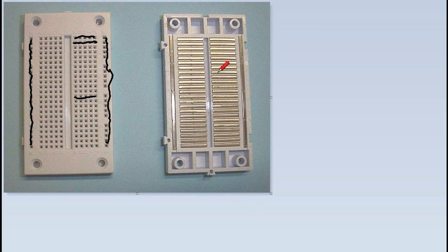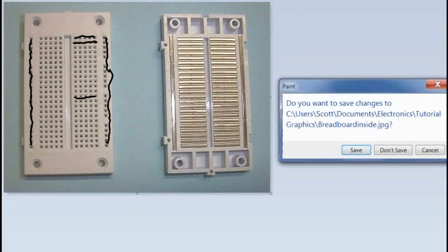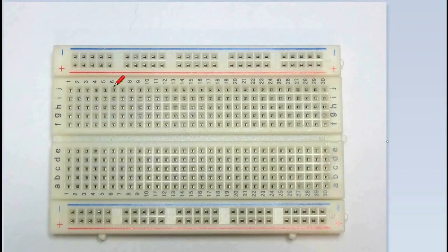So now let's go back. Now that you've seen the inside of the breadboard, let's go back to the last picture, the half board. I showed you this on Adafruit. You can buy these almost anywhere. You can see the little metal holes in there. This is where we stick our resistors and our power supplies. Let's say we have a little battery, and the positive side will plug into this rail, and then you can put the negative side here.